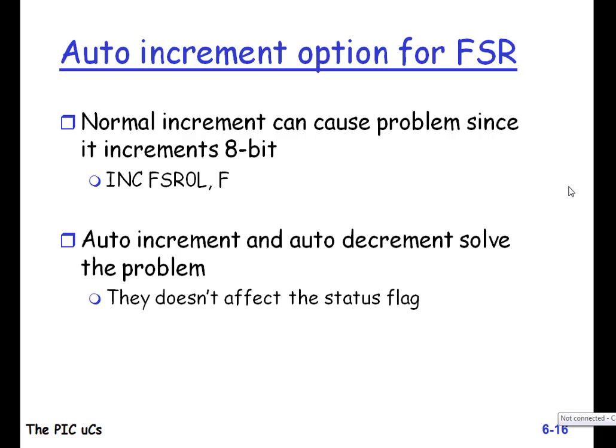Next is the auto-increment option for FSR. Normally, incrementing can cause problems, since it increments only 8 bits. Auto-increment and auto-decrement solve the problem.